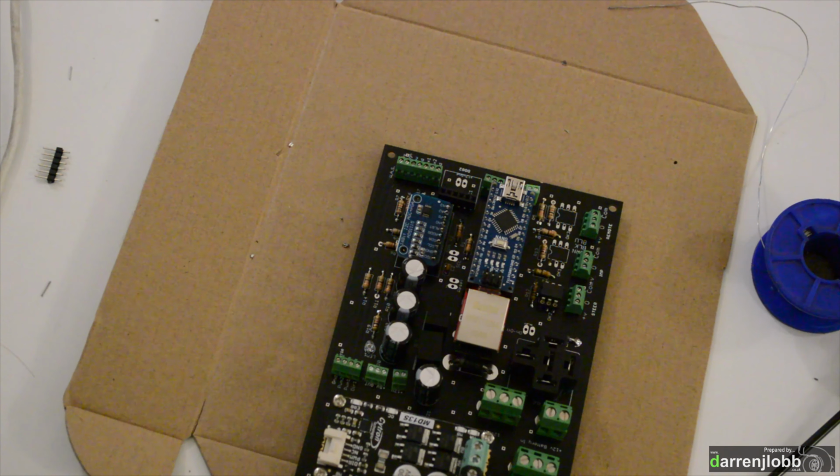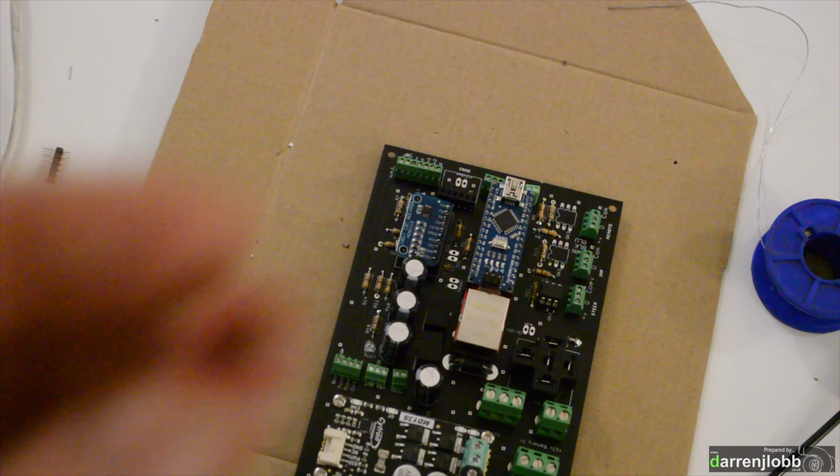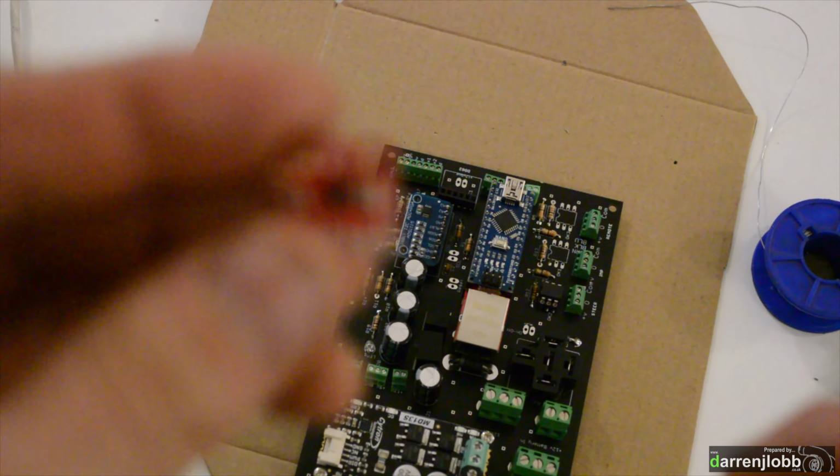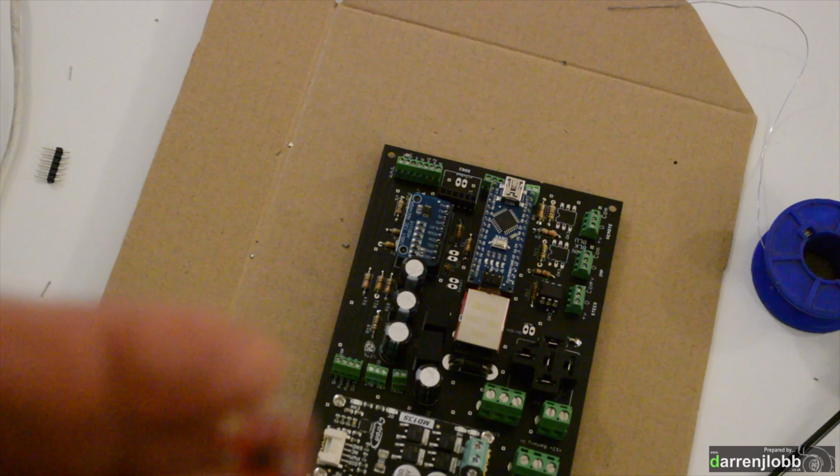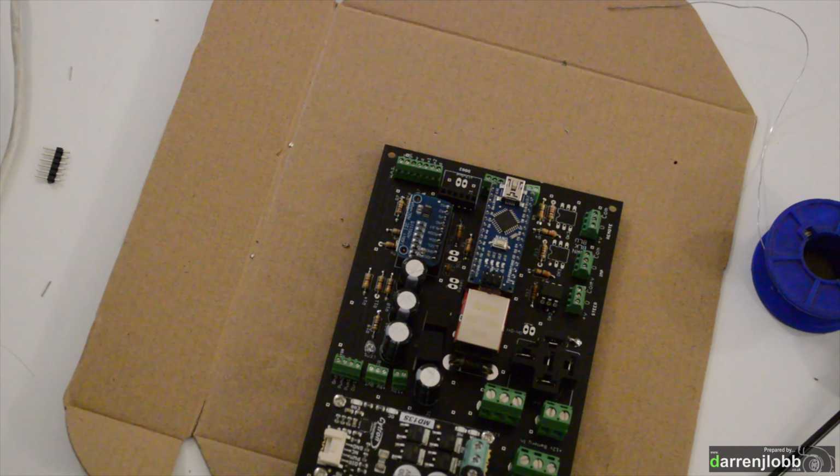If you look closely at the board, there are two arrows on it. The arrows basically indicate X and Y, or Y and Z, or whatever you want to say, because it's a four-way. It can sense either way, so we're only going to be using one of them. So if you mounted the PCB flat, you'll want to use a different set of headers to if you mount the board upright, because obviously you need this chip to be sitting level with the plane of the tractor, so that this board itself is using one of its axes as the tractor is rolling left to right. So just pay a little bit of attention to how you're planning on mounting this before you actually solder your headers on, because you'll be screwed once you have, really.